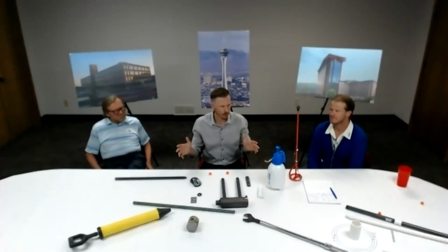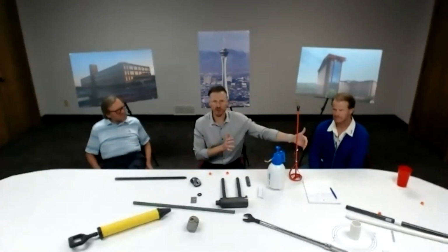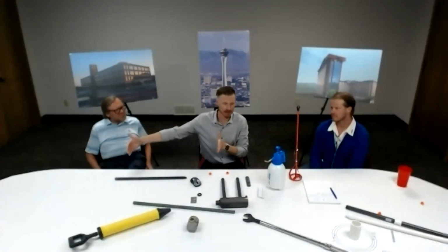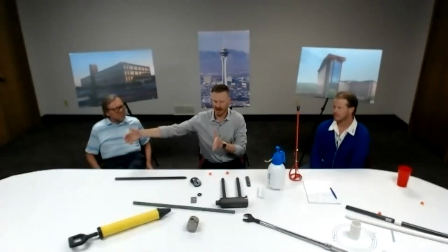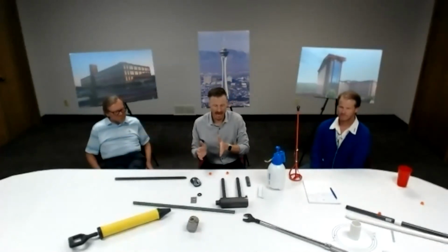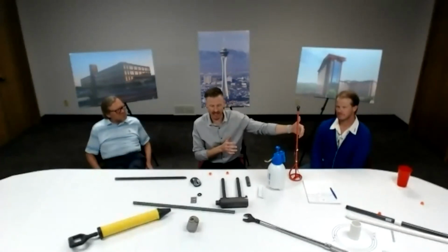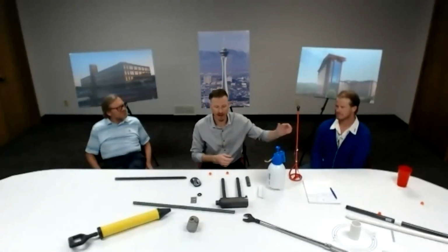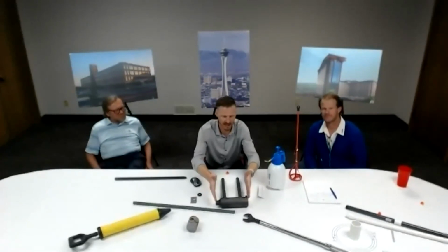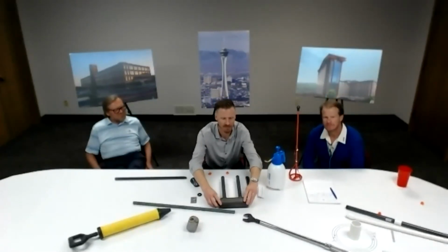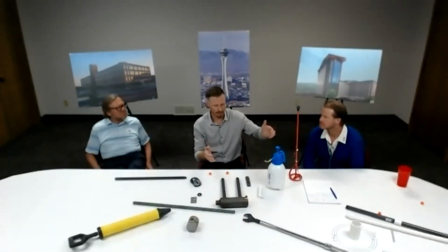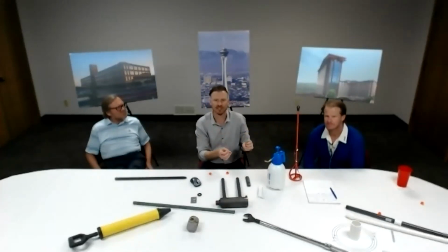Okay, so right now we have a 4-foot threaded bar, which the lap length is 48 inches, and 48-inch laps with number 4s, number 5s, easy to get full capacity, 6s even. And then on the other side, the loose bar, we just make it a 5-foot bar, because the coupler itself is about 8-9 inches long. So that extra foot, when it pulls out, you still develop the full tension capacity in the bar.